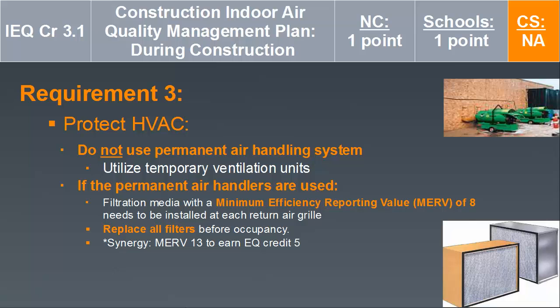If you're trying to achieve indoor environmental quality credit 5, these filters that are installed before occupancy need to be a minimum MERV rating of at least 13. Remember those MERV rating numbers for each credit for the test.